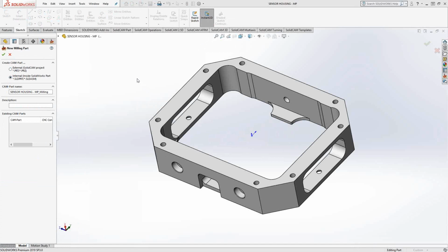And anyone who doesn't have SolidCAM will still be able to open up the SolidWorks aspect of that file, but they'll have to load this massive file that has all the SolidCAM stuff as well, even though they can't even see it. Now, how that's done is basically the folder would just take the name of the SolidWorks part file and call it _milling, and then you would just see it as a folder in that internal.